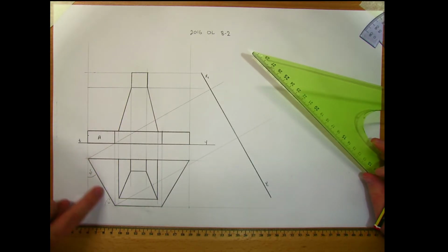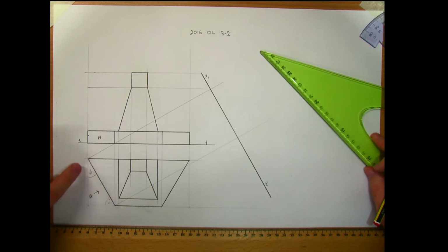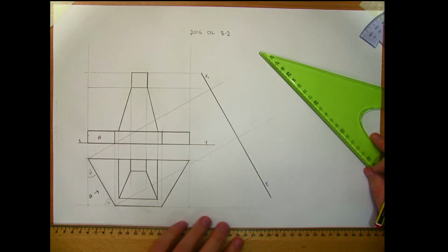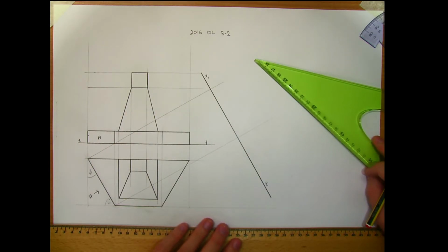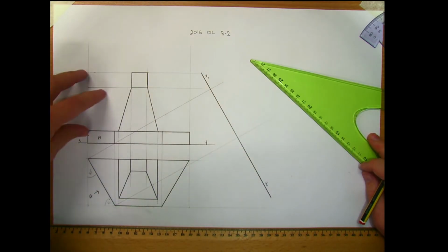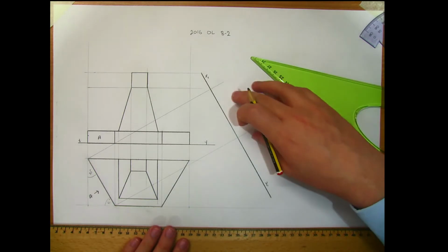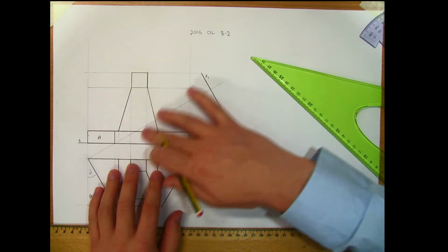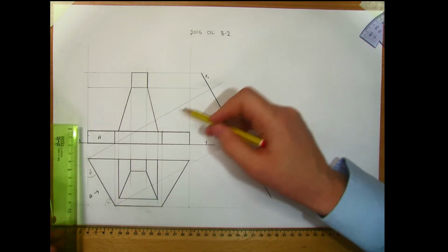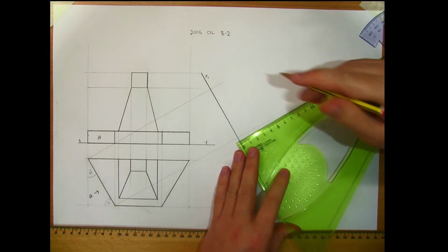First, I'm going to start with surface A. So we've established that this is the width of surface A, so I projected this point up here and this point up here as well. We're asked to draw an auxiliary elevation. So for an auxiliary elevation, we're going to be working with our heights from the previous elevation. Anytime you're doing an auxiliary view, you skip the adjacent view and measure from the third one back. So the height is going to stay the same. All we're doing is looking at it slightly differently. So this is going to stay being 15 millimeters.